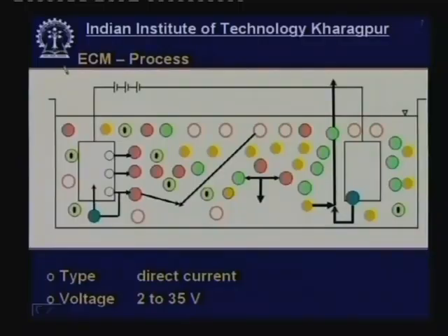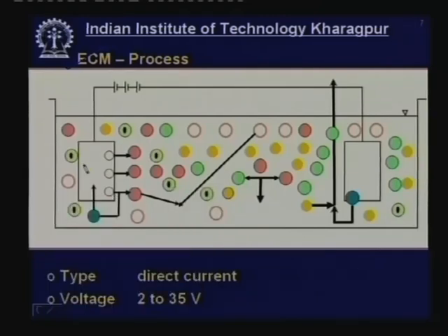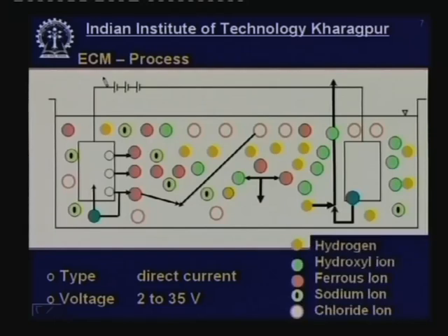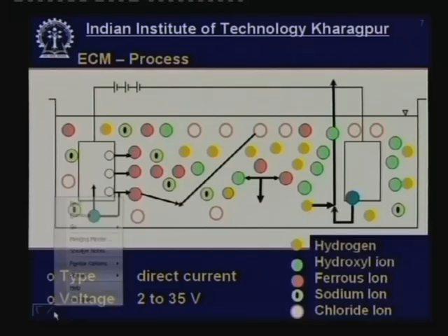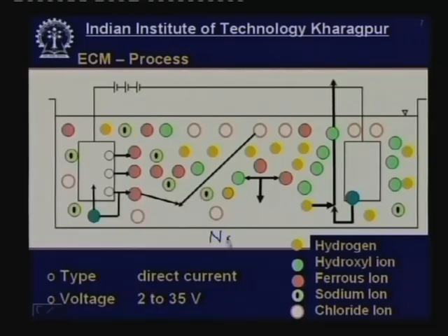So, let us come to the graphics. This is describing the electrochemical process, and this is my workpiece and this is my tool. Once we apply a potential difference, then what happens? Because of electrochemical dissolution, this is my electrolyte, and the electrolyte could be sodium chloride electrolyte.